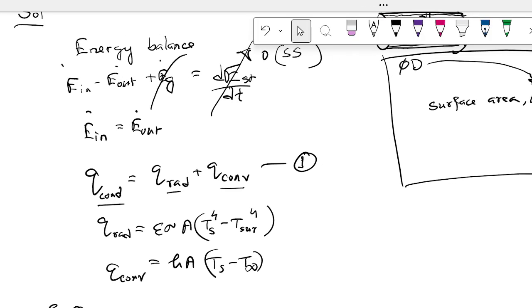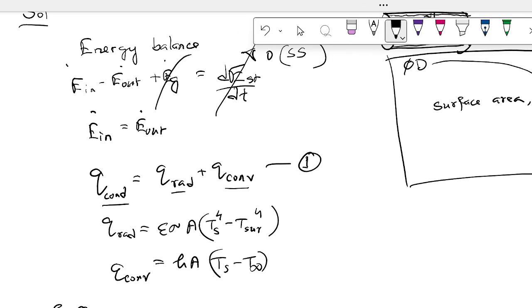Okay, and then I have the convection, obviously, which is 10 watt per meter squared Kelvin. I want everybody to solve the problem with units. This is the standard way of dealing with the math, so you can cancel out all the units and come up with the final units of interest. And then the area is 7.85 meters squared, and 423 minus 298 Kelvin.